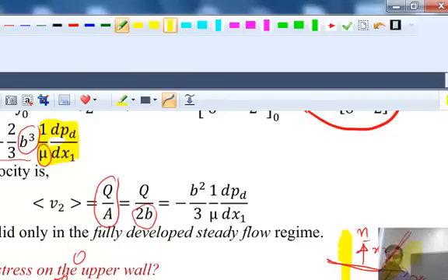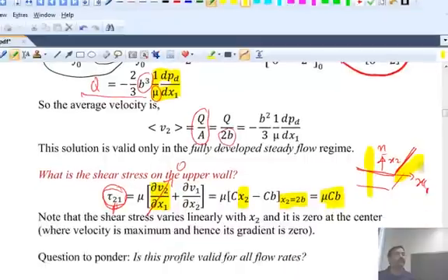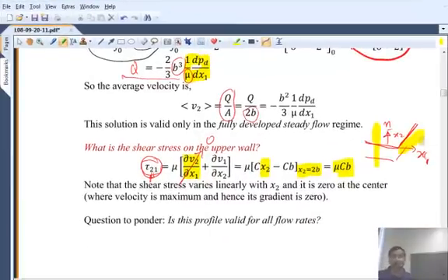So if I calculate, for example, tau 2,3, what do you think that would be? 3 being the z direction perpendicular to the board. That is the x3 direction. And I'm saying calculate tau 2,3 for me for this particular problem. What would you expect that to be? 0, right? Because there is no flow in the third direction, so there are no gradients of the velocities in the third direction, so that component must be equal to 0.